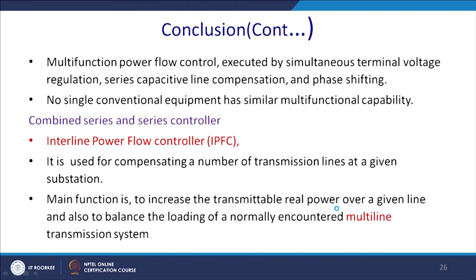Multifunctional power flow control is executed by simultaneous terminal voltage regulation, series capacitive line compensation and phase shifting; all is possible, so it is quite a versatile device. No single conventional equipment has similar multifunctional capability. Thus UPFC is basically the solution.